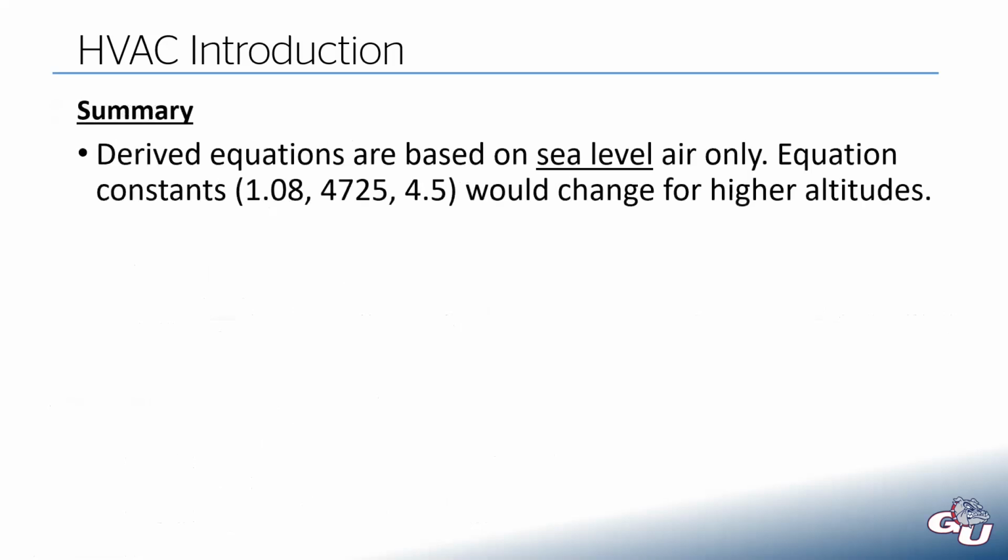Important to note that these equations are based on sea level air only. So those equation constants of 1.08, 4725, and 4.5, at higher altitudes, that would change the density of the air, which would change those coefficients.